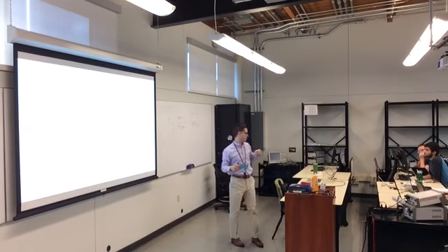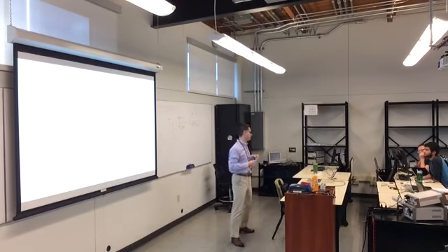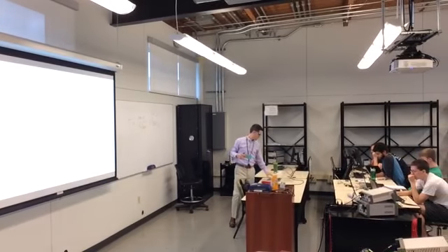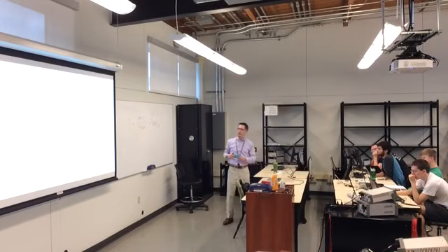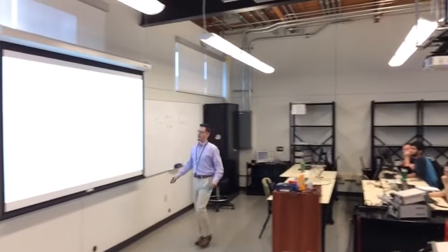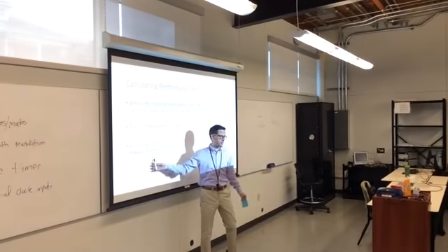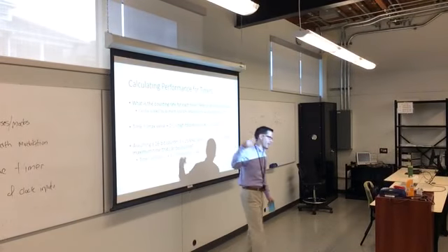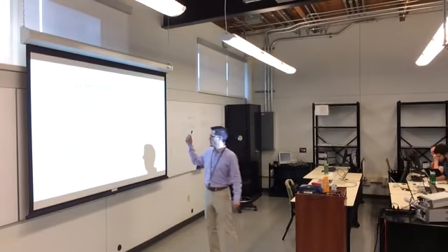So I'm going to cut it down. So if you punch all this math in, you've got 2 to the 16 minus 1. That's the biggest value that timer can hold. Plus 1, so these are a wash.